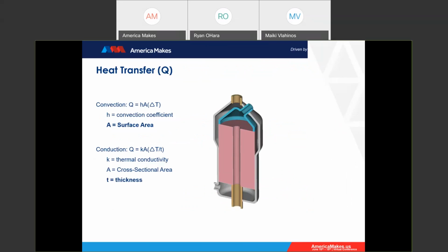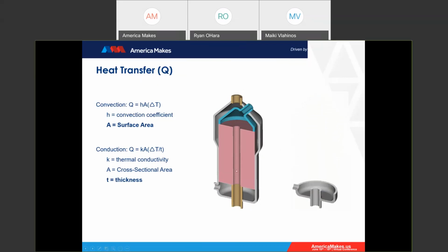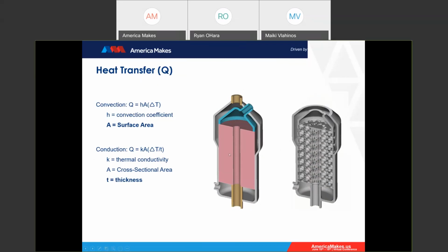To describe the idea behind this design, hot oil enters through the top, impinges on this blue dome, moves around the outside, enters the red cylinder, which is going to be a gyroid core eventually, and exits out the bottom. Hot fuel enters through this left port, comes up through that cylinder or the gyroid structure, and exits out the top right. And you can see the internal workings of that in the GIF on the right hand side.